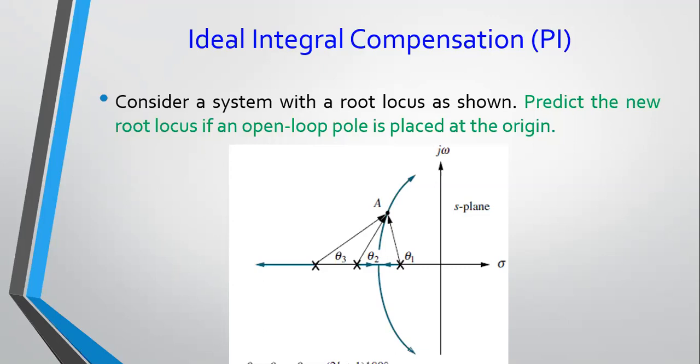If you have, for example, a type 0 system and you are trying to control position here, we said normally you would have non-zero steady state error, so your Kp would be finite. So you have a steady state error which is finite, not 0. But if in this case your system type is type 0, and then you add an integrator here, it means you are increasing the system type to 1. The type 1 system is able to track position. So if you do that, your system would now be able to track position with a 0 steady state error. So this is basically what we're doing.